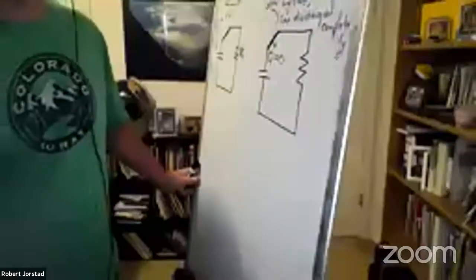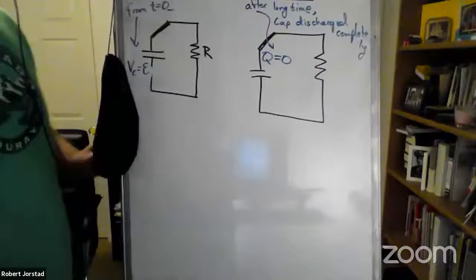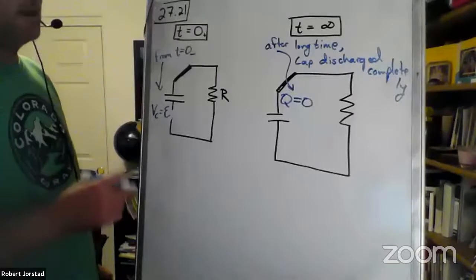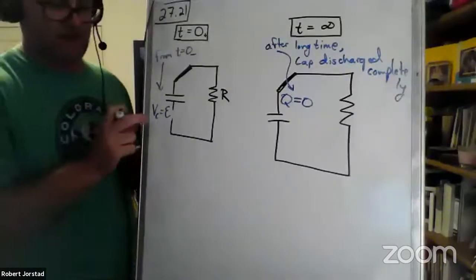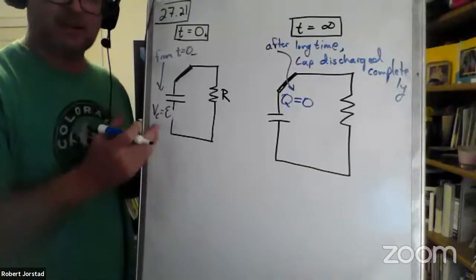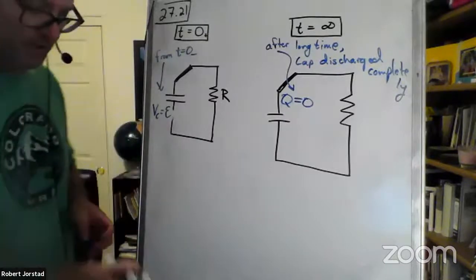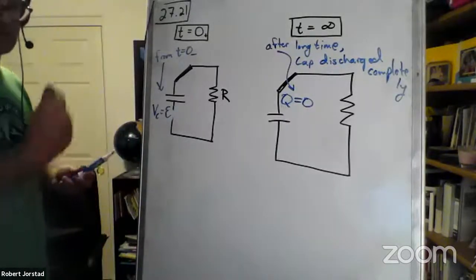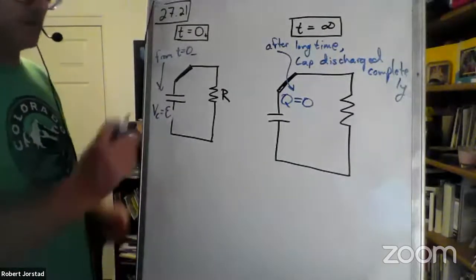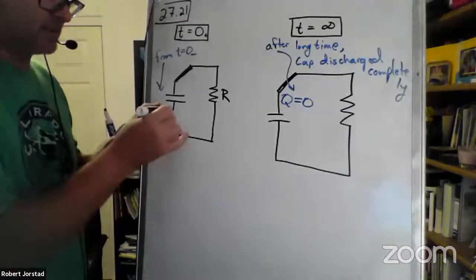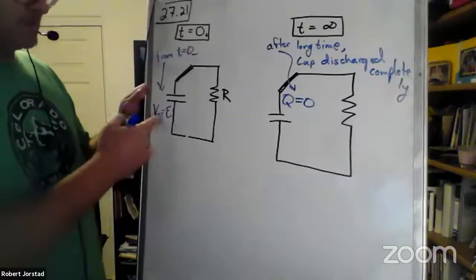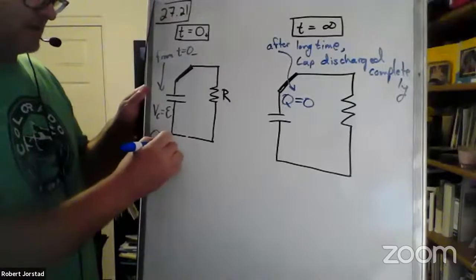Okay, so you've had a second to look at it. I'll share my whiteboard. So again, what do I know? From the 0 minus picture, I only get one piece of information, what the voltage on that capacitor was. We say the capacitor preserves its voltage. That's the same wording that you will hear in an electrical engineering course. Capacitors preserve their voltage. Inductors preserve their current, if you're curious. More on that later. What is an inductor? We need to know chapter 30 first. Okay, so now as soon as I know this, boom, I know the charge on the capacitor, that's EC.